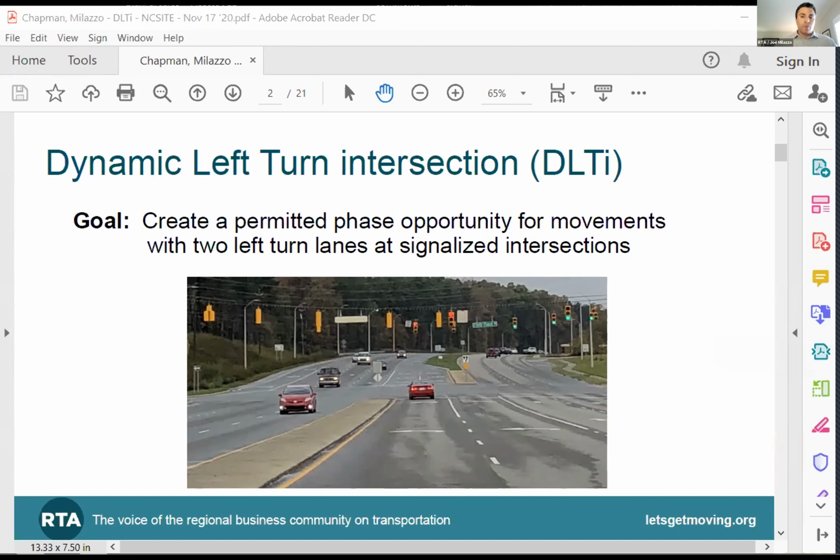The positive ones are numerous. One, it's more efficient during that phase. There's no conflicts. You're providing clear direction to the motorist. You're getting effective platooning. You can minimize the duration of the phase as a result. A lot of very positive impacts of making that protected. Protected only left turn has several negative impacts, of course, and we know those.